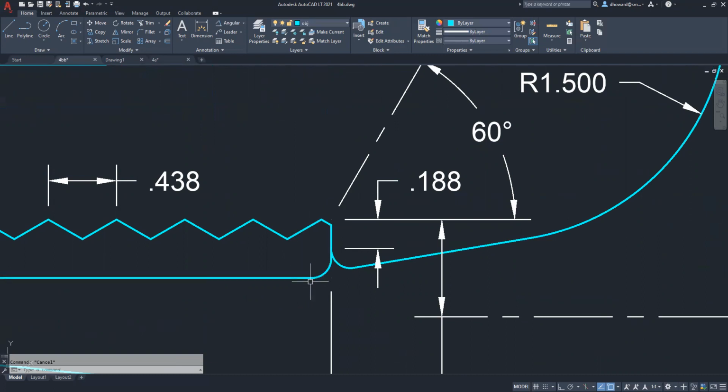So this petal top was 3/8 of an inch. So the distance from the top to its center is 3/16 or 0.188. And that's where I have the fillet tying in, okay? And then of course this line was going to tangent on the pivot itself. Does not need to be dimensioned.